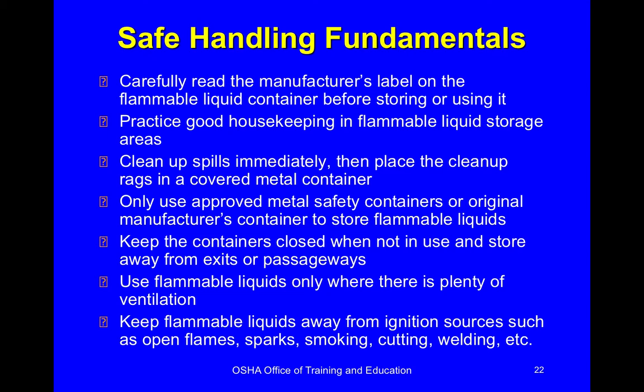Use approved containers. Keep containers closed when you're not using them. Also, like the flammable cabinet, close it when it's not being accessed. Only use flammable liquids when you have enough ventilation, and keep them away from ignition sources.